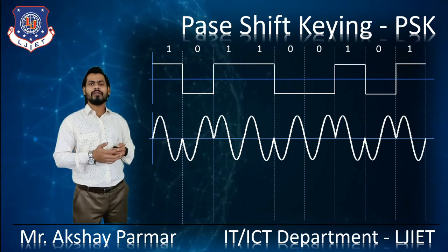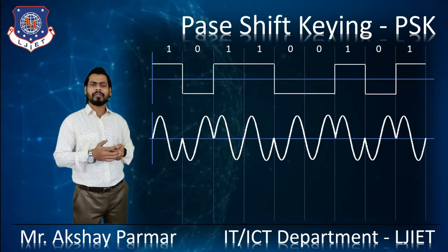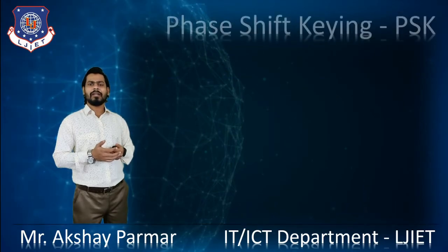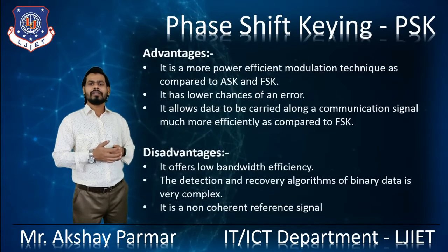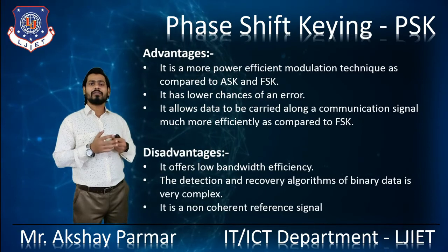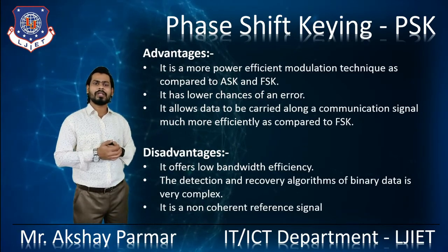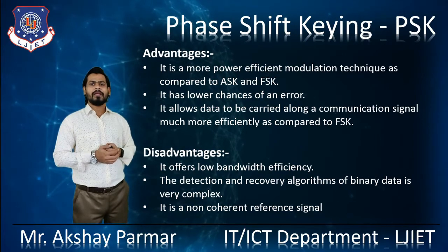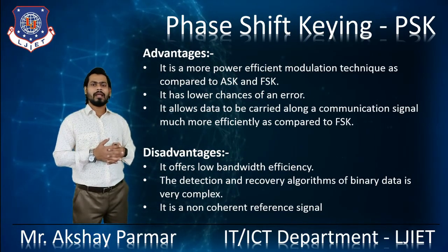So this is about how phase shift keying works. After that, let's see its advantages and disadvantages. The advantage is that it is a more power efficient modulation technique as compared to ASK and FSK. It has a lower chance of error, right?